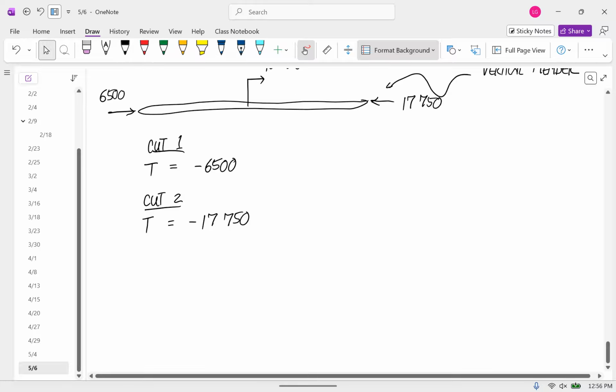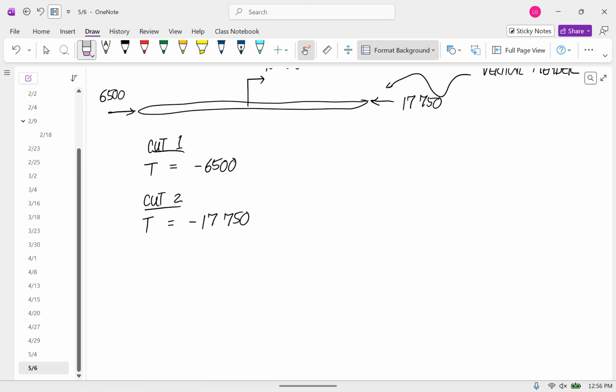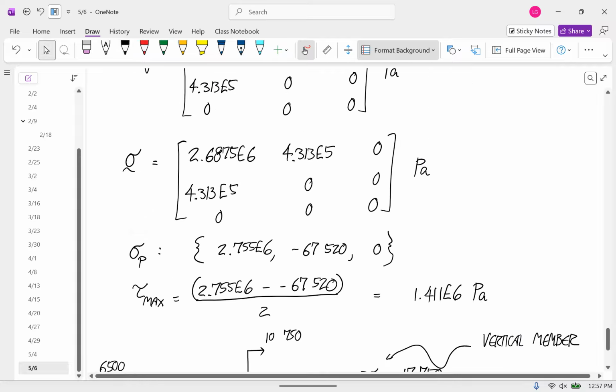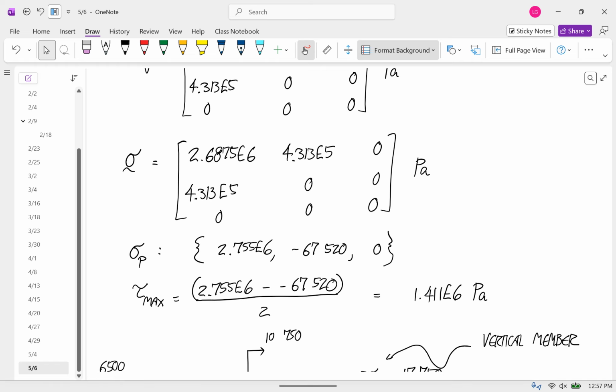And now we can go to the elongation. So we're not including the x components of the forces applied. Right, because all it asked about is the elongation. It didn't ask for the deflection. Deflection is horizontal. What's the difference between elongation and deflection? The deflection is a movement of points perpendicular to the long axis of the beam. Oh.